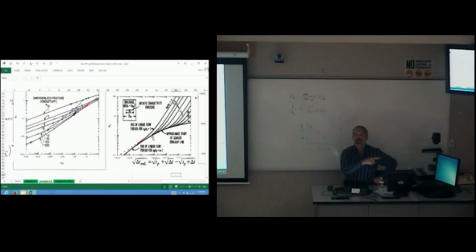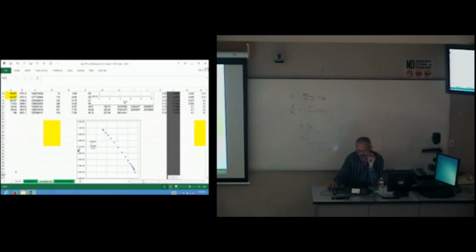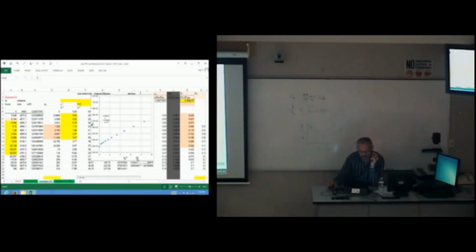Let's say we were back in radial flow. Knowing everything I know right now, the first thing I would do is calculate the pressure derivative. And if it's flat, then I'd make my specialized data from that flat data, and I'm basically done. Okay? On linear flow, I actually have a derivative. So let's go there.